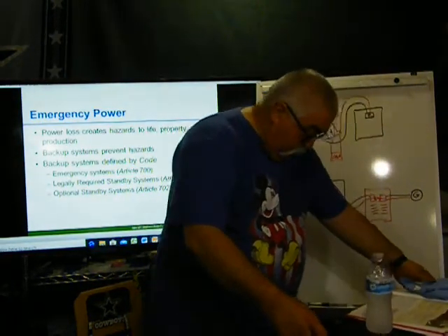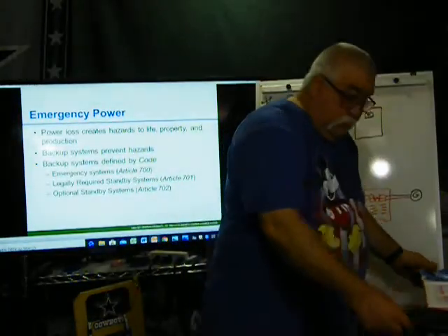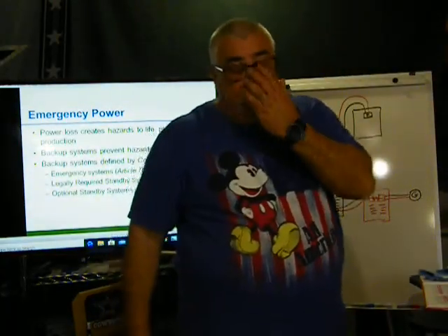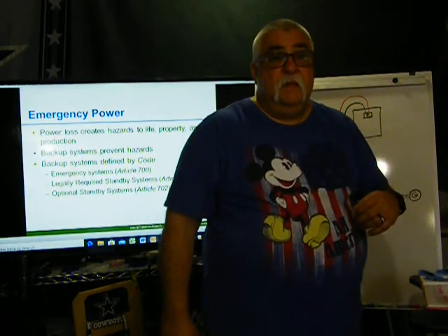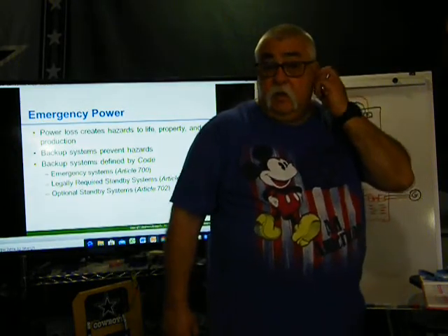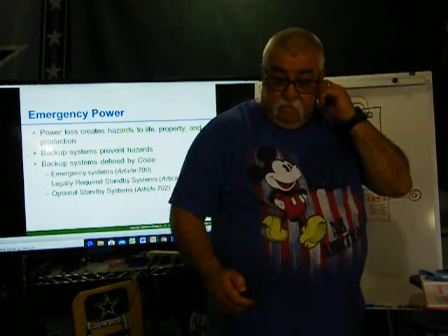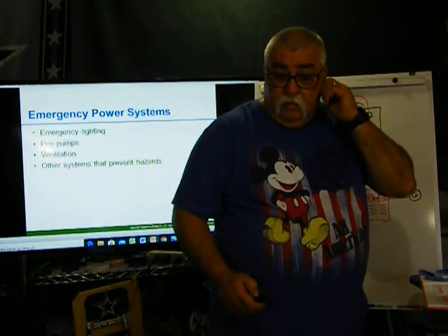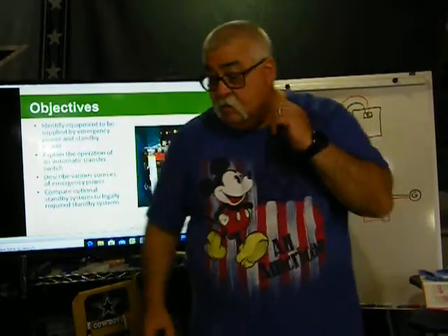You know, when I worked at the hospital, we had generators. The generators have to be tested, so we'd have to come in bi-weekly and do generator tests to make sure that they were working. We have to exercise the transfers. Our transfers were automatic.